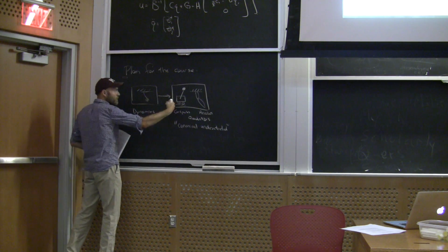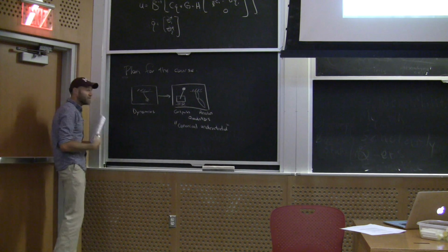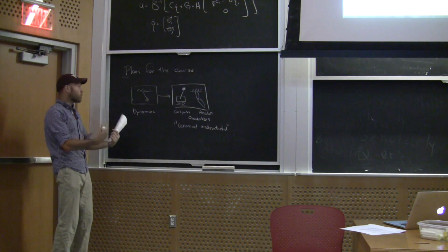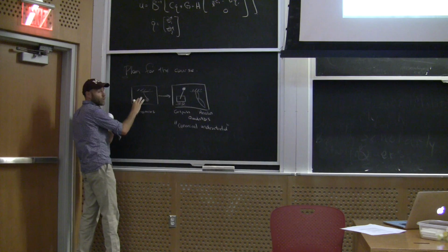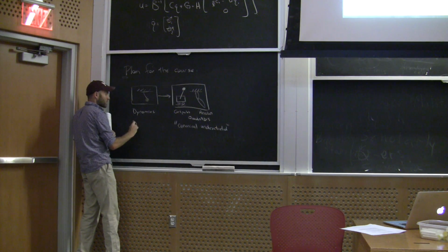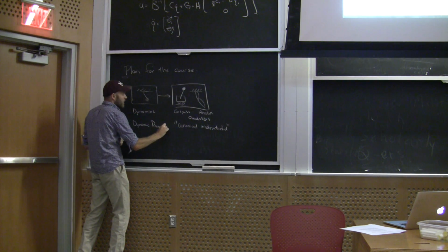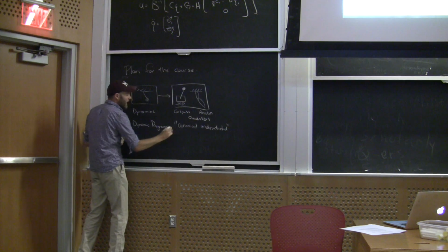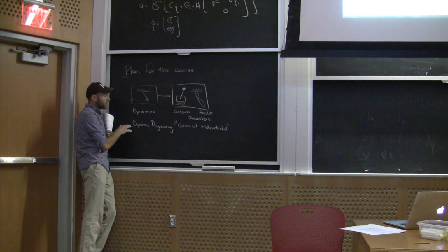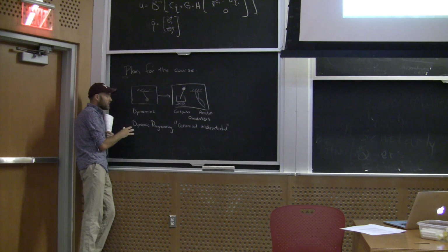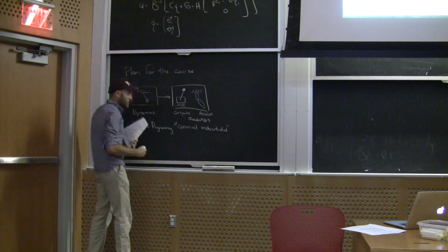Every time we introduce another robot, it'll motivate a few more algorithms. And I don't want to give you algorithms without giving you a robot that needs that algorithm. So it turns out that we're going to be able to do everything we want to do with the pendulum just using dynamic programming. And that'll be a nice way to introduce the ideas of writing control problems as optimization problems, using the language of dynamic programming. But dynamic programming is already going to start breaking down when we want to control the canonical underactuated systems.